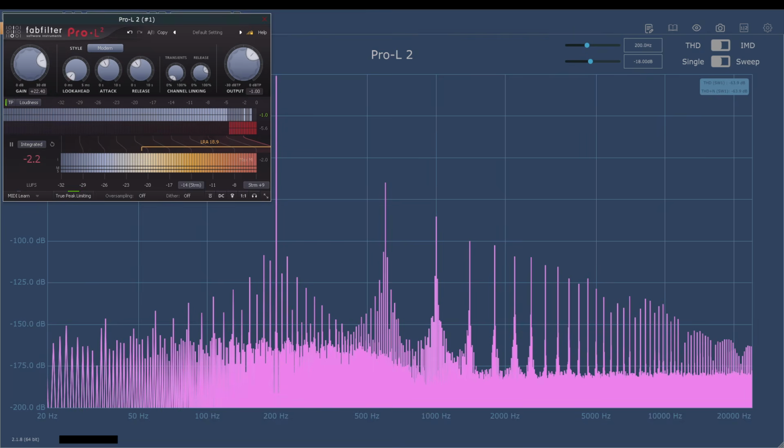And there's the second reason this test is flawed. One of the most important criteria for a brick wall limiter is the way it handles transients. Perhaps the most important criteria, as in my opinion, transients should normally be the only part of your audio that ever hits the limiter threshold. And where are the transients in this sine wave test tone? It's just a steady state. This is not a signal that any limiter will ever be presented with in real life. How do you expect to measure the limiter's transparency with this?